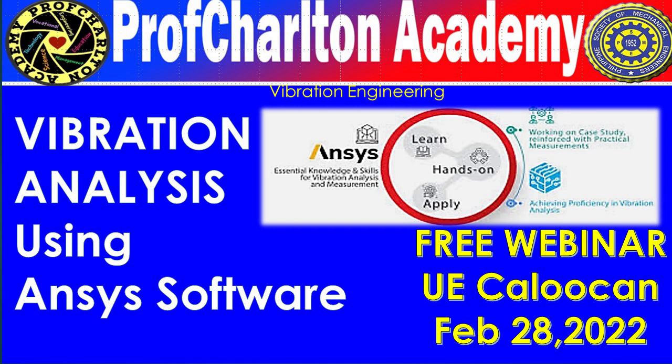When you run FEA, you will not get a single result. Normally, when you do calculations, you get only one number as a result. But in reality, the stress will not be constant throughout the model. It will be a changing stress. That is the advantage of using numerical methods. For the results, we have something called a probe. I'll use this probe to explain. When you click on this element, this portion, the stress is 28 megapascal, whereas this portion is 26, and here it is 19.